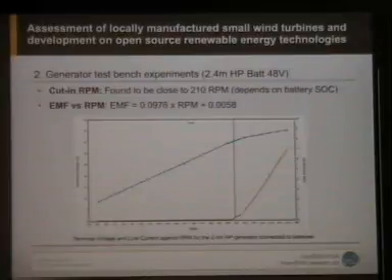The blue line is the terminal voltage. The first part is a straight line where it's just EMF, and then you start having the voltage drop on the stator coils and the cable as current flows through, and then you have the red line, which is the line current.